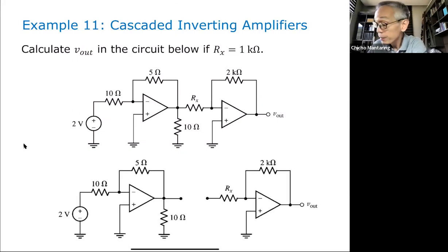So it's like this, no? I will separate the two. If I connect these two together, in other words, will the output of this change? And to determine that, I have to know what this output will see. So what will this output see when you connect this? What it will see is the input resistance. And we discussed input resistance already previously.